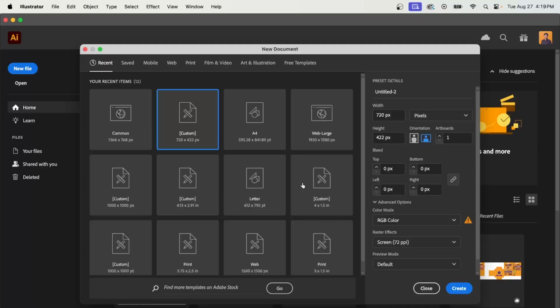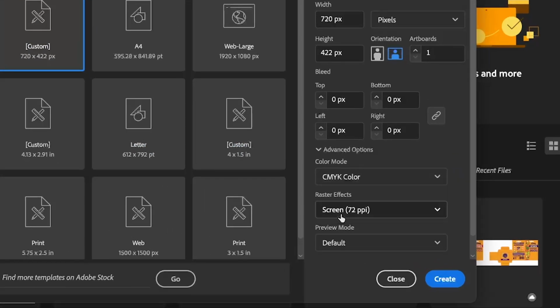One thing to keep in mind is that colors can appear slightly different on print than what you see on the screen. So when you are doing packaging design, in Adobe Illustrator for example, your document should be in the CMYK color profile. That way you have the most accurate representation of the final printed color. And colors may appear slightly darker on some materials like uncoated paper or matte materials because they absorb much more ink compared to glossy materials.